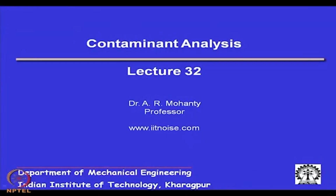Now we will begin module 4 of this course, wherein we will be discussing the other techniques of machinery condition monitoring, that is normally the wear debris analysis as it is known, and the other condition monitoring techniques like motor current signature analysis, and how non-destructive test NDT techniques like ultrasonics, radiography, acoustic emission and also thermography are used to find out faults in machines.